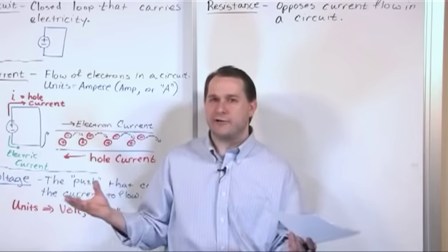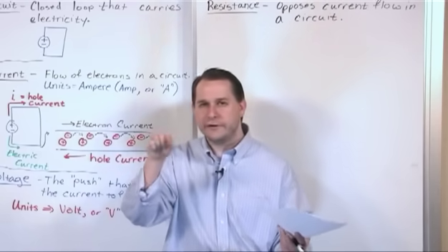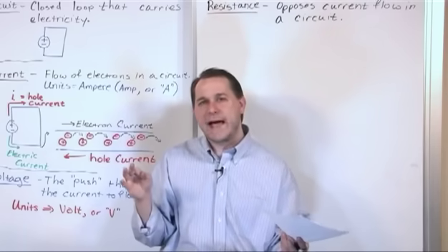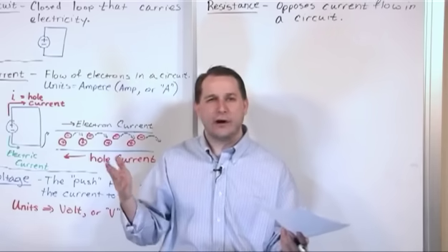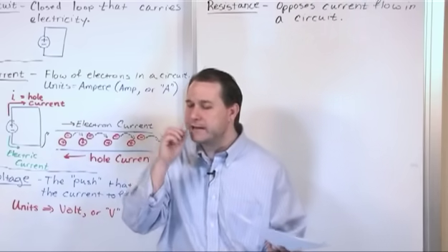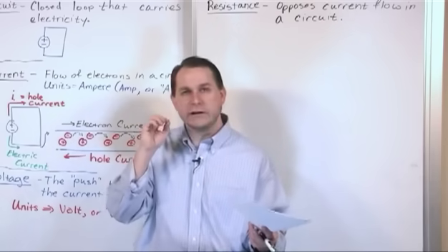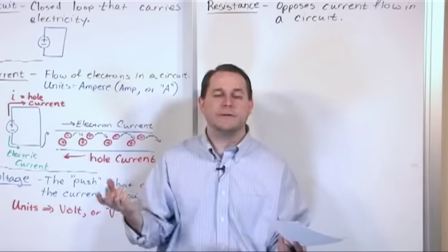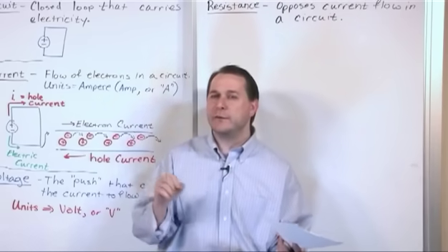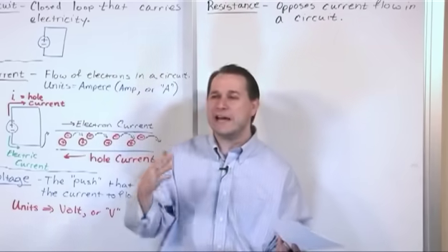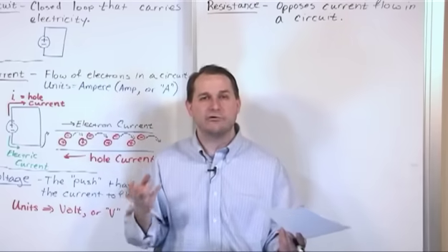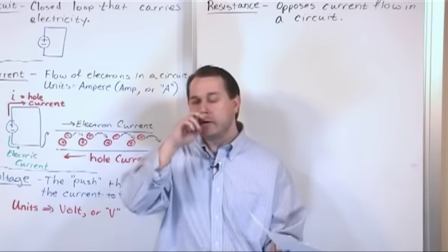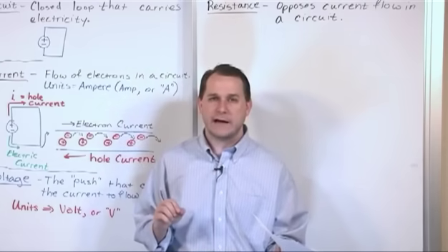Now let's compare and contrast that. Let's go back to our coffee stirring straw. Very, very tiny diameter. So for that one, to get any kind of air movement through it, I've got to blow pretty hard, and I can feel it in my lips. I'm really blowing, because we say that the resistance of that smaller straw is much higher. The resistance to airflow is higher because it's physically constrained. You cannot force that much air through that straw very easily. I mean, you can do it, but you have to blow really hard. So we say the resistance is much higher for that one.